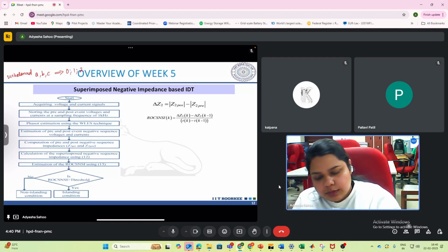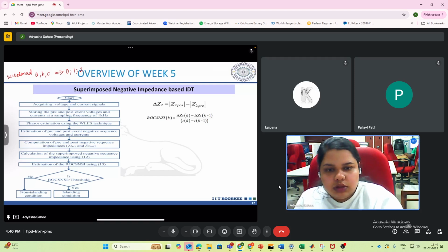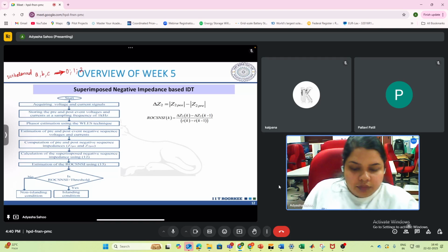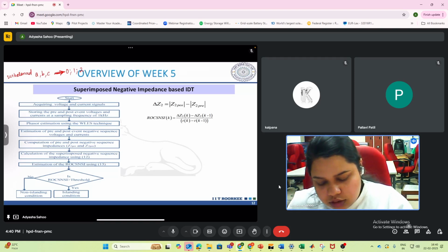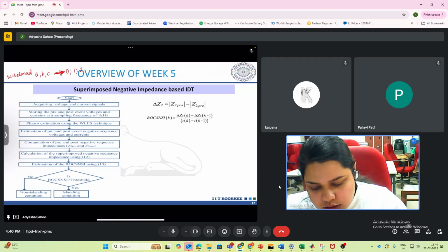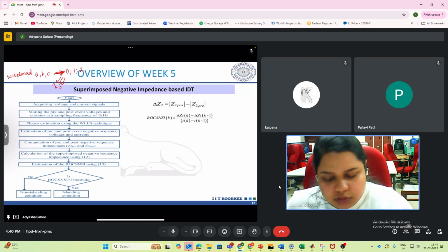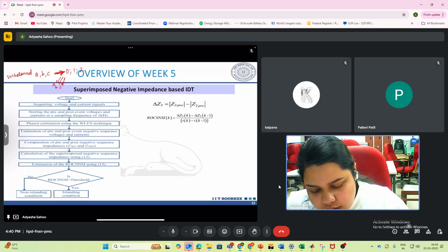So here, what happens is you decompose these voltage vectors, both their magnitude and the direction, such that these ABC unbalanced quantities can be represented as three sequence networks. So in the zero sequence network, all the three ABC phases don't have any phase difference between them. They are in the same phase.